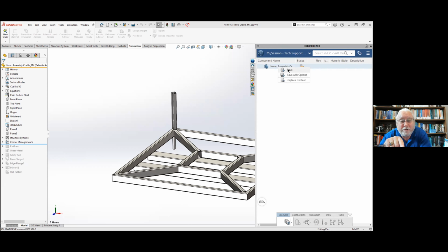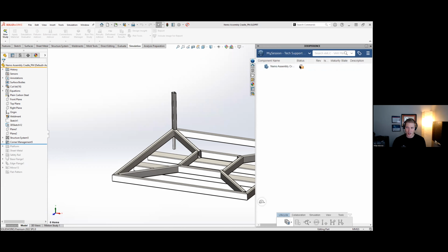So right now, the thing on the screen in SolidWorks is saved to your local drive. If you go to this thing here, this tab with 3D Experience, you do what you're doing, and then it saves it to the cloud. Exactly. And it's telling me here in the status that it hasn't been saved to the cloud yet. Even if I hover, it tells me. And once I save it, it'll tell me all sorts of other stuff, like it'll be Rev A in work. And that's just an add-in for SolidWorks. So at that point, is it still on your hard drive? At that point, I can delete it from my hard drive. It wouldn't actually matter. It still would be there, but from that point on, I'm only going to work with it out of 3D Experience.